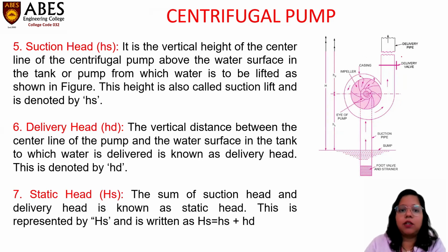The other is suction head. It is the vertical height of the center line of the centrifugal pump above the water surface in the tank or sump from which water is to be lifted, as shown in the figure here. This is Hs, the suction head. It is the vertical height from the center line of the centrifugal pump above the water surface. This height is also called suction lift and it is denoted by Hs.